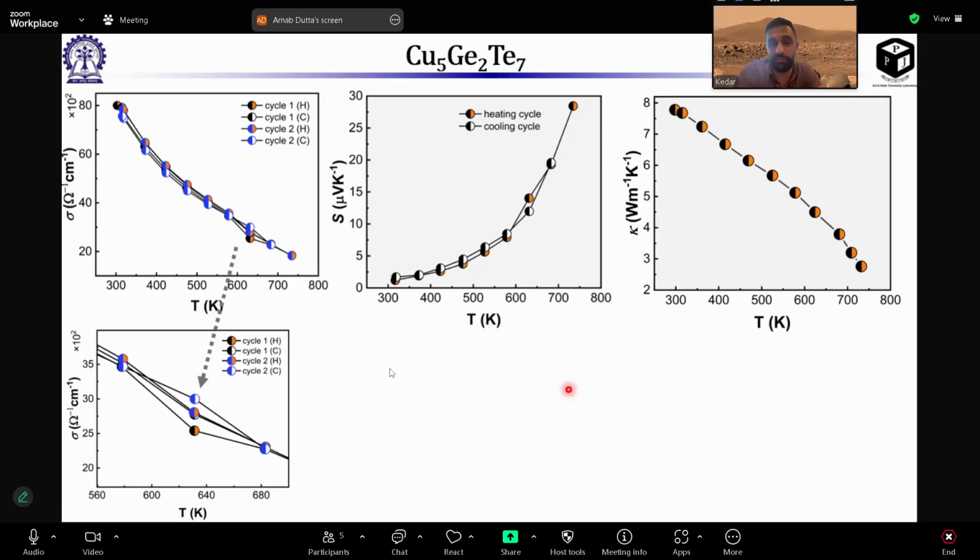Actually, we've been trying this phase pure for a while. We tried silver antimony telluride initially with its pure phase. That's also a eutectic compound. I think it's slightly silver poor, and I forgot the exact phase diagram. But we didn't succeed. Then we tried some other materials too, and this is a relative success, like the copper tin telluride story.